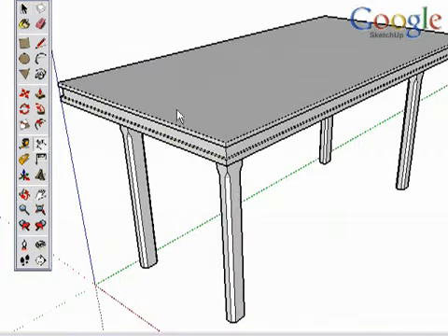When you have created models and need to communicate measurements, use the dimension tool. You can pull dimensions off edges or between any 2 points, and even off of arcs and circles to show the radius. Look at other videos for more tips on being accurate with specific tools in SketchUp.